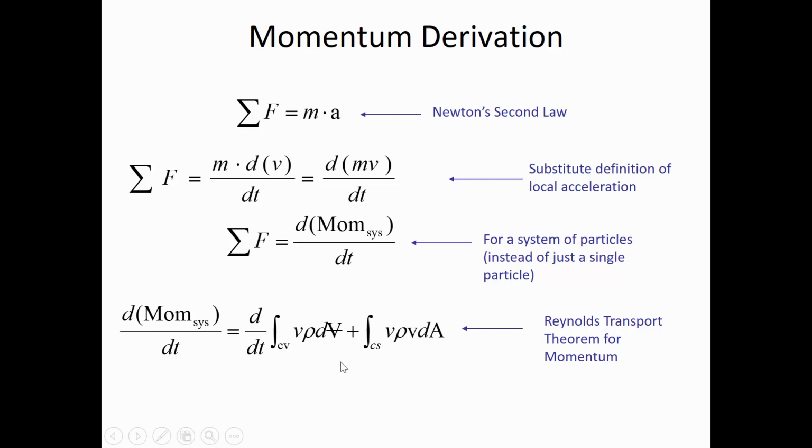And so how this is different from the Reynolds transport theorem that we've seen before is, in the past when we were doing Reynolds transport theorem, we had, let's just use the flow in and out through the control surfaces as an example. In the past, we had some differential area dA that the stream was passing through. That was the cross-sectional area. V is velocity, the density, and so those three terms together, the density, the velocity, and the area through which it's flowing, was the mass flow rate m dot.